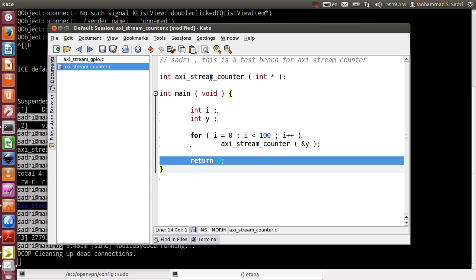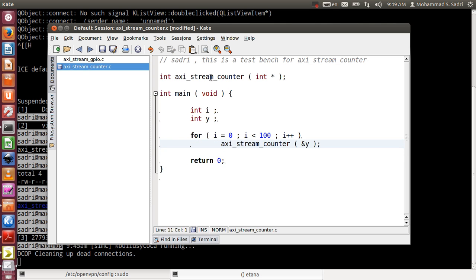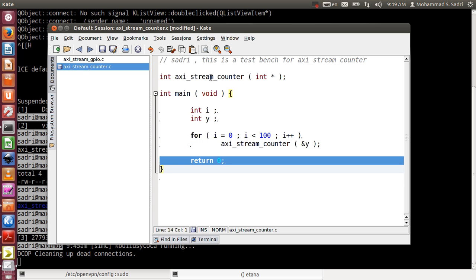If the return value is non-zero, then Vivado HLS understands that the test operation has not gone as we were expecting, and it stops the simulation with an error message. For now, I don't intend to compare the outputs of this unit with any other reference. I just want to see them, and I directly return 0.